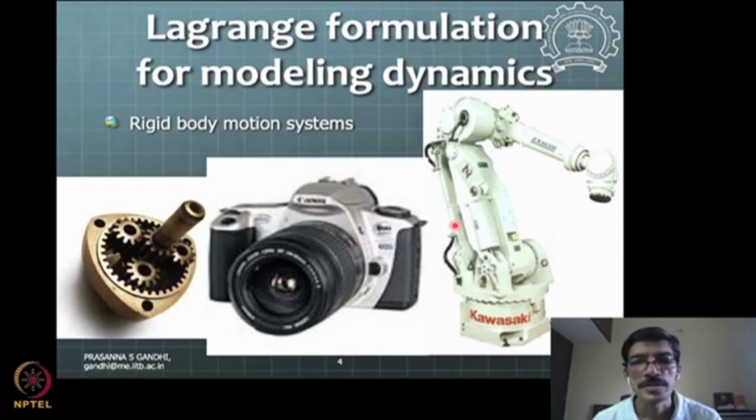All these systems can be very nicely modeled by using Lagrangian dynamics, and based on the equations that you obtain in some generalized form, a control can be proposed especially for systems which are fully actuated, where every robot joint has actuation, no joint is left unactuated. Then you'll get nice controls that can be developed later.